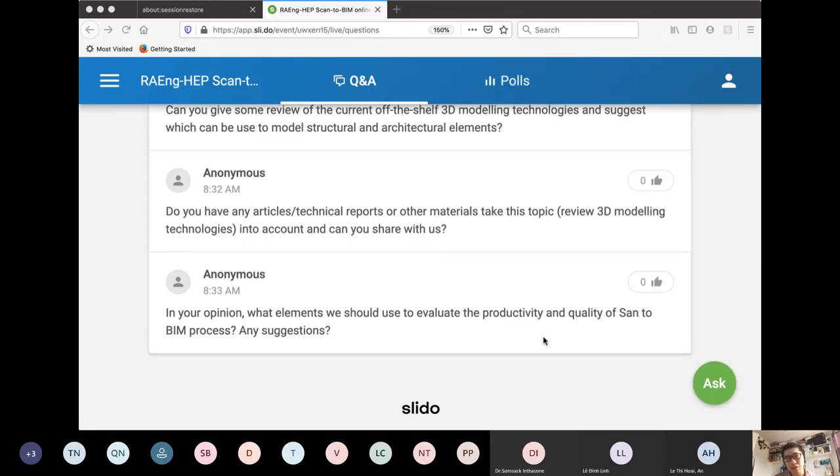I know the new Leica Geosystems software has auto stitching. It saves a lot of problems. For other software, I'm not sure whether Faro has it or not. The stitching process is the longest and the least accurate process that we have at the moment. Okay? Yes, that's my opinion. Thank you. Okay. All right.